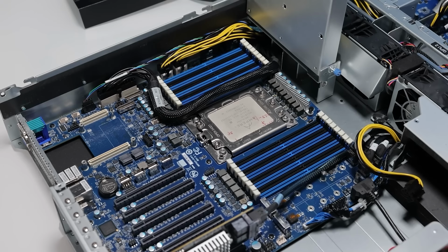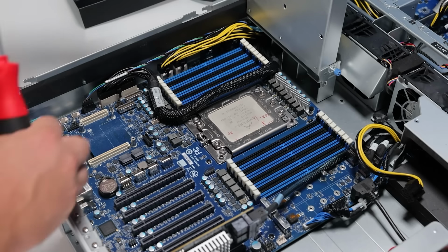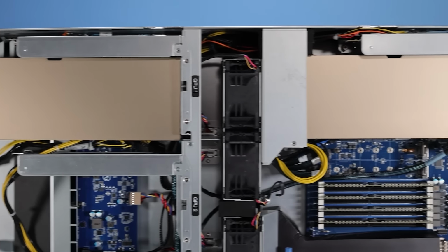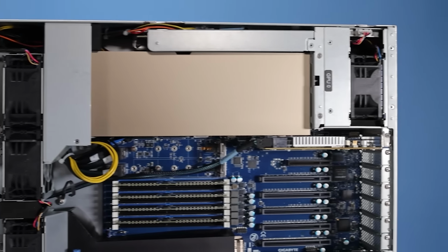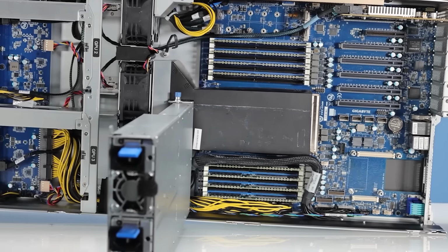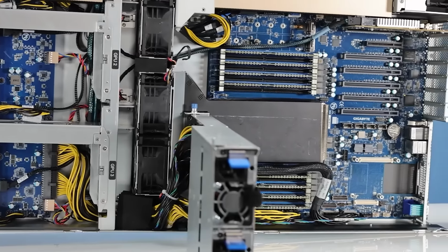So as a recap, this Gigabyte G242 P32 has 128 ARM cores, and these are ARMv8 cores. We have 2 NVIDIA A100 80 gigabyte GPUs. We also have DPUs, we have some base networking, and we still have more expandability in terms of storage and PCIe slots. And the server uses so little power that we can run it on a standard North American 120 volt 15 amp outlet, no problem. So with that, let's start running this thing, and I want to show you what it looks like.